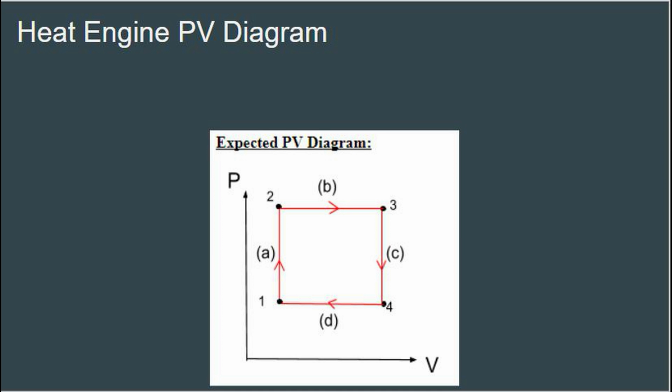The final state change in the cycle is from state 4 back to state 1, and this change is isobaric compression. At state 4, air has reached P1. At this point, the volume will decrease to its initial state as the pressure stays constant.